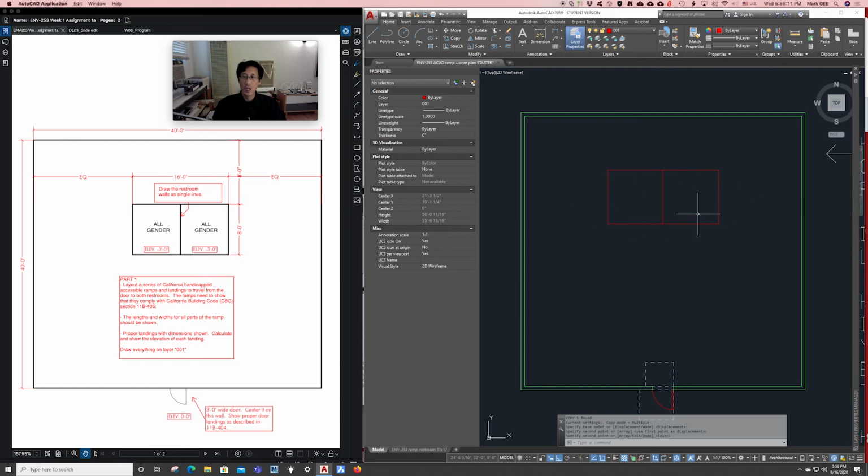The restrooms are blocked out, as we say, and the rest of the drawing for the ramp is up to you to lay out and draw using lines. Stick to right angles if you can, please. I think that's the easiest thing. There's no need to get fancy in this drawing. It's a very prosaic, very functional drawing. I just want you to understand what the lengths of the ramps need to be, where the landings need to go. Okay. One last thing before we move on is how to print the drawing when you're done.